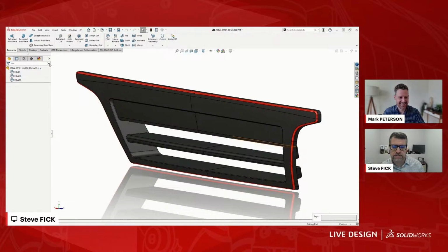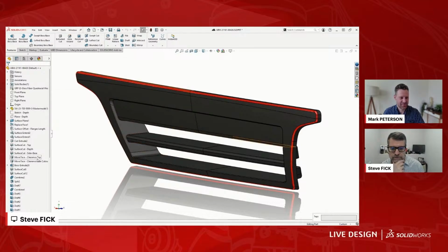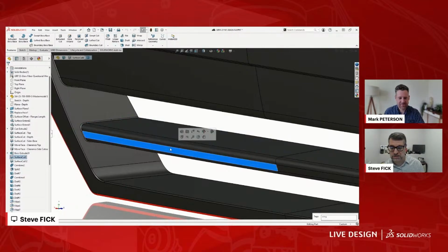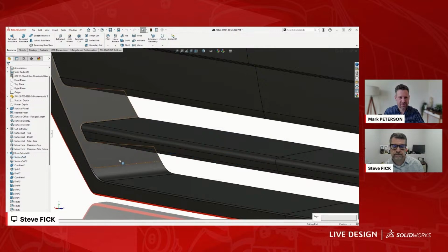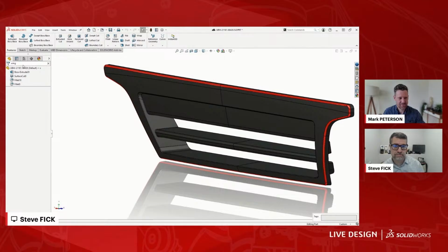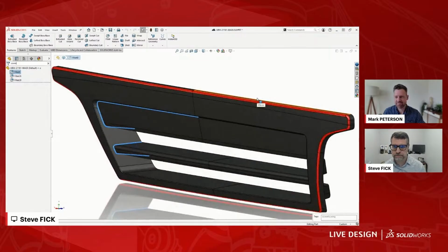And the other use case for this that's handy is, we talked about the size of this feature tree. A lot of times you've got an element of your design. For instance, this is the wing on this part, and it's made up of a boss extrude. It's made up of a fillet. There's actually a surface cut in here. And then there's a cosmetic fillet over here. If you were to take the approach of using a folder, getting those all into a folder could be a little tricky, just because you do still have to adhere to the way that the feature tree solves. But with tags, you can tag all those things with the tag wing, and it doesn't matter where they are in the feature tree. Now you basically can group them together based on the design feature on the part, as opposed to using folders or things like that. So this is a super cool way of getting to just what it is you're looking for and organizing your features.